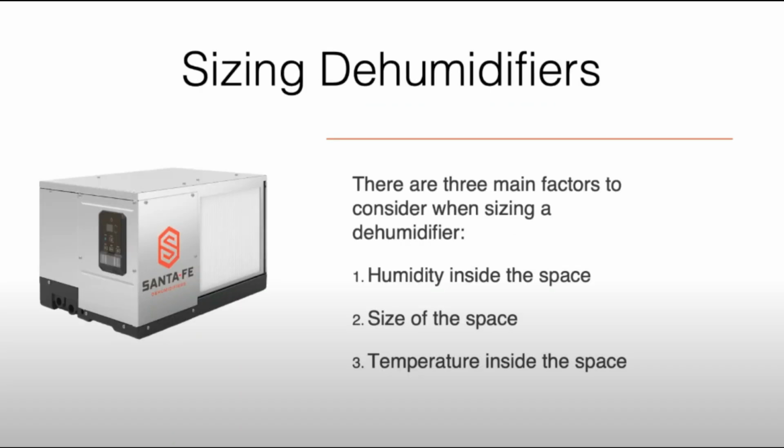Sizing dehumidifiers. Based on the 2021 code, as we mentioned earlier, the sizing is based on manufacturer's recommendation. There is no regulation on the manufacturer on how they set their parameters on this. You need to go into the crawl space and measure the RH, but that's just a snapshot in time. You can use data loggers to get a better understanding. That brings us to the size of the crawl space area. This should always be measured during your inspection.